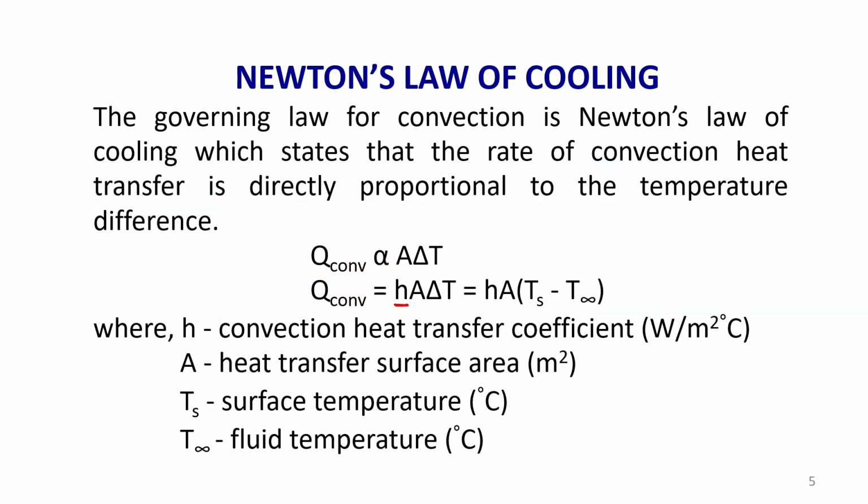Where h is the convective heat transfer coefficient in watt per meter square degree centigrade, or watt per meter square Kelvin also, it is correct. A is the heat transfer surface area in meter square. Ts is the surface temperature and T infinity is the fluid temperature.